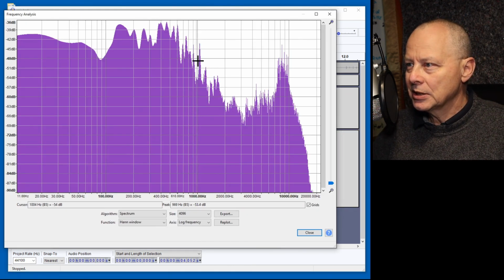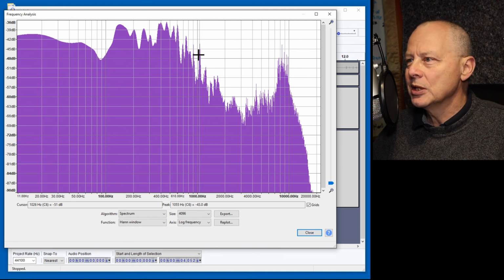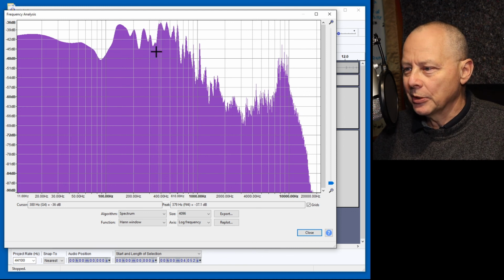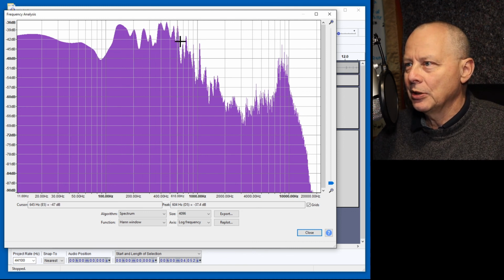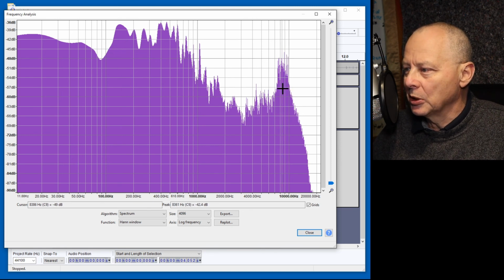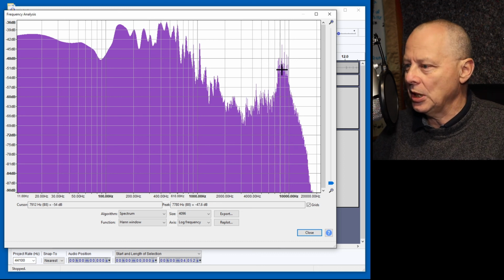There's a spike at 1034 Hz, so you see the spike here, that's due to the electrical noise, but it's less than the power in the speech area, which is around here, 200 up to whatever. So this is the area where the speech is causing the power, and then up here this is the hiss, probably the electrical noise again.